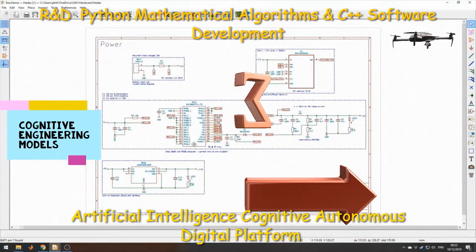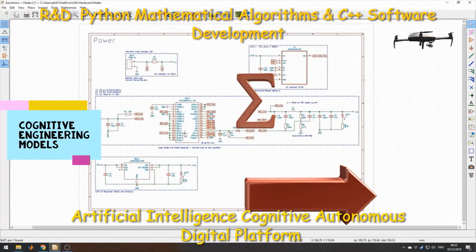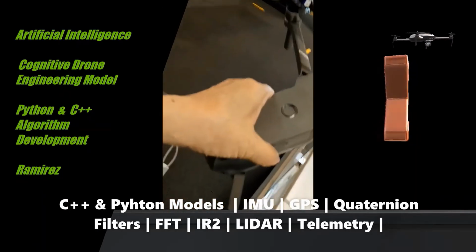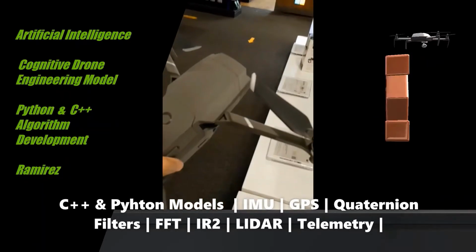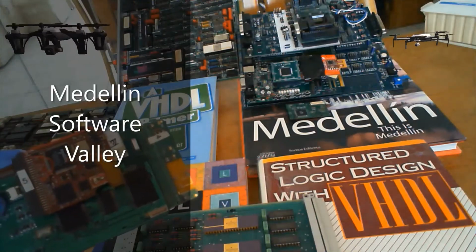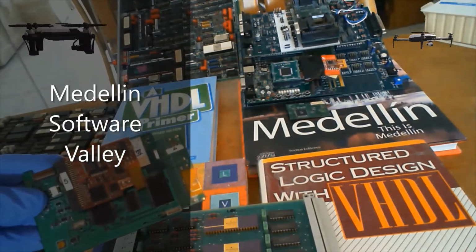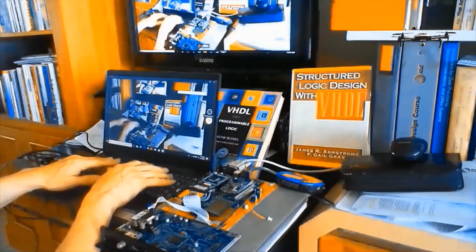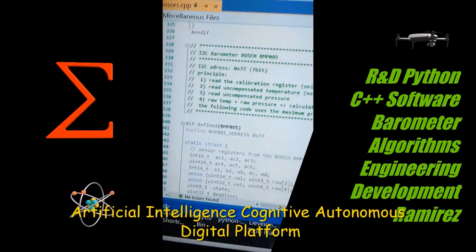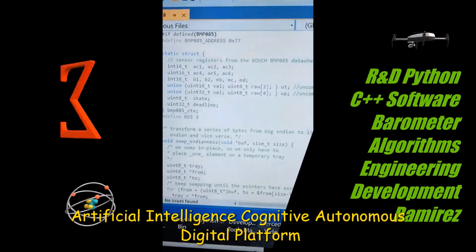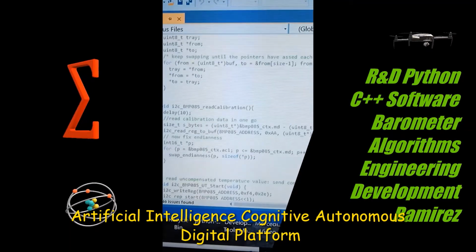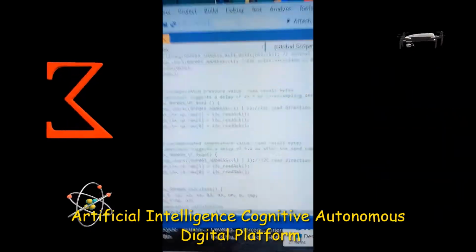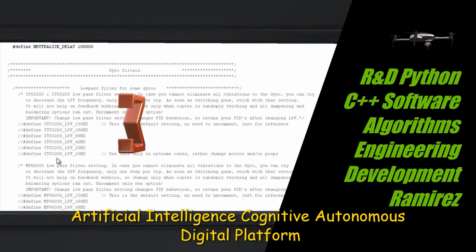Software and firmware. Set up the software framework and firmware methodology. This includes defining the type of multi-copter environment by using the config.h, which is essentially the configuration file. Then set up and configure the motor's main throttle and set up the I2C bus interface.